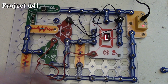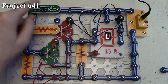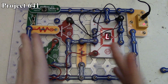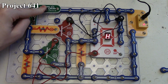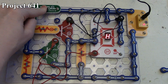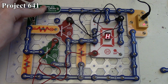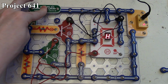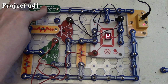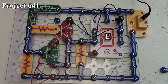If I turn on the slide switch, the output condition does not change. Although this is true, this is false, and it's still false here because this is an AND logic gate. So the catch is both conditions need to be true before we have a true output on our 7-segment LED. We have a true condition for our slide switch and a true condition for our press switch because both of them are turned on, and by that we get a true or high condition on our 7-segment LED. So that's how the AND gate works, project 641.